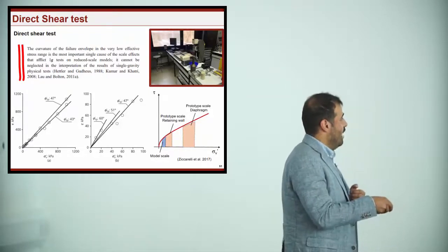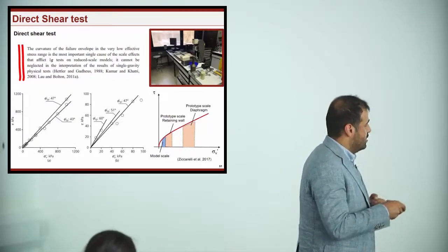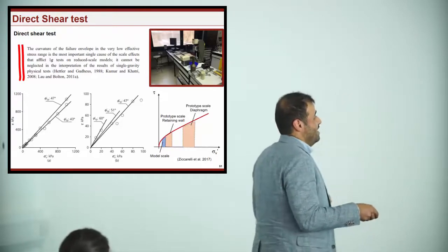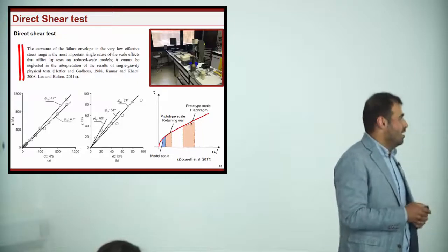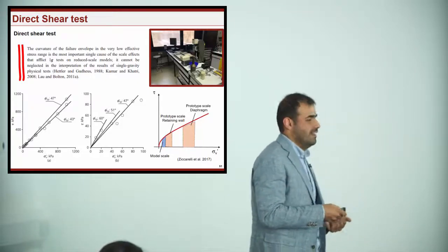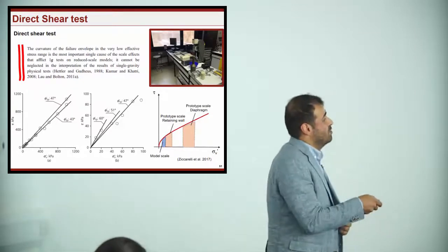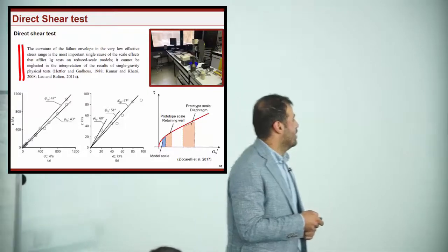For this reason, at this level of stress the shear strength angle is very high compared to the one of the critical state condition. We can say that actually we are not so far from the conditions we have for a retaining wall that has a height of 2-3 meters, compared to the condition of a diaphragm wall, for example, which is another situation.